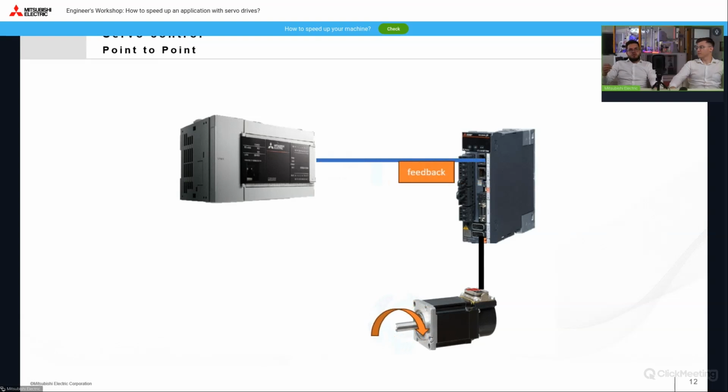This uncertainty can cause problems. Therefore, when you have several drives, you need to be sure that each one is in the right position, and you have to wait until one has finished moving before the next one can move. In short, the drives must not pass each other because this can lead to a collision.